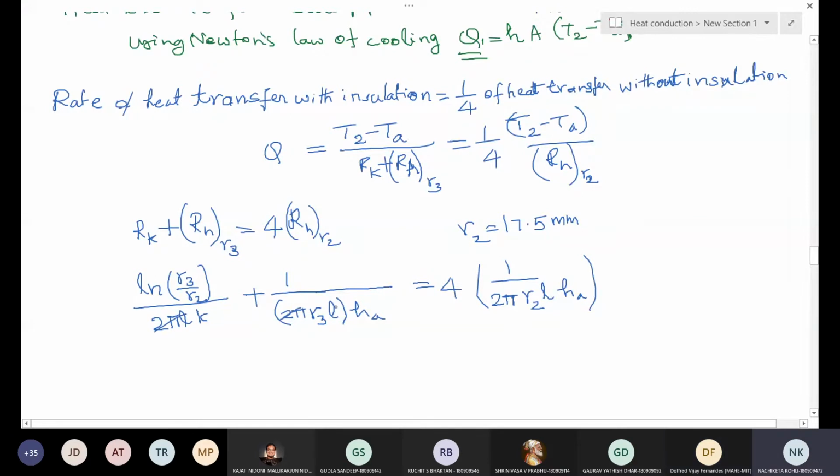So in the first term, you have cancelled the R2, R3 in the denominator. Which one? So isn't it 2 pi LK R2, R3? Sir, there won't be R, right? No, 1 minute. Which one you were talking? 2 pi? So first term, 2 pi LK R2, R3. No, that is spherical wall. Okay, cylindrical it will not go. Spherical it will be 4 pi K R1 R2. So R3 will remain here, R2 will remain here. So leave it as it is.